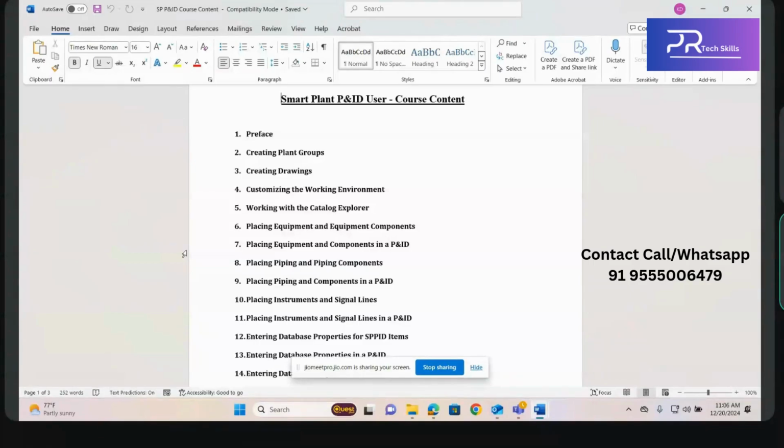In AutoCAD, you might have seen, you just open one drawing from the plus sign, and you can draft, and every time you need to save it, right? No, it is not like this here. Whatever the plant name, area name, unit names under the area, and the drawings structured under the unit, this is how the plant structure you need to create in this software.